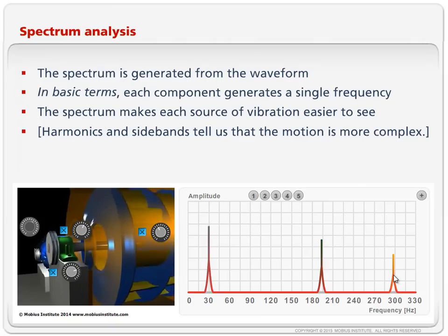So if someone talks about vibration frequency, you might hear them say, oh, it was the 10x peak. What's a 10x peak? Well, the 10x peak is 10 times the running speed. And a vibration analyst might think, oh, I wonder if there were 10 blades in that fan or 10 vanes in that pump. That's the sort of thing.